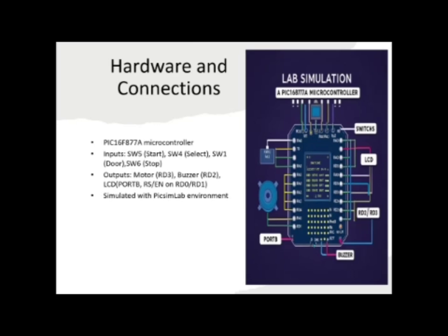Hardware and the connections. In the simulation, the PIC16F877A microcontroller is connected to four switches for start, select, stop, and door status. The outputs, simulated motor, buzzer, and the LCD screen, are connected on port B. The simulated environment is used in Picsimlab, which models the hardware virtually.